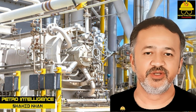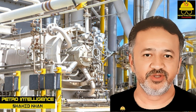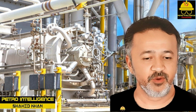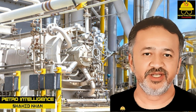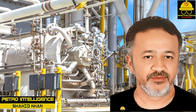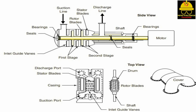Axial flow compressors. In the industrial environment, axial compressors are the compressor of choice for jobs where the highest flows and pressures are required. Unlike centrifugal compressors, axial compressors do not use centrifugal force to increase gas velocity. An axial flow compressor is composed of a rotor that has rows of fan-like blades, as shown in picture. Airflow is moved axially along the shaft.